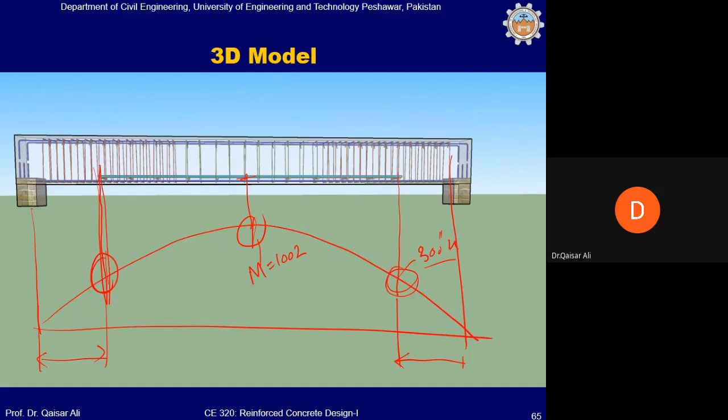This we will discuss in some other lecture, but at the moment you can see that all these 5 bars are not carried to the support. The 2 bars in the second layer have been curtailed at some distance where they are no longer required, because the area of steel required was calculated based on this maximum M, which is only in this region. After that, the bending moment decreases until it becomes 0 at the support. So very close to the support, the bending moment value will be very small. So to save some money, we can curtail a few bars.